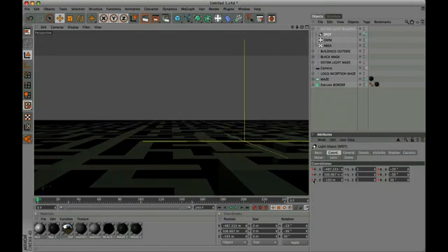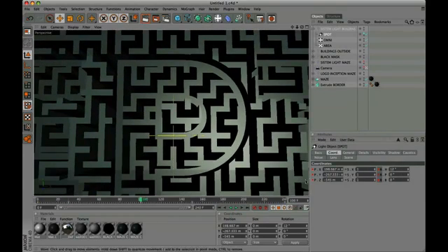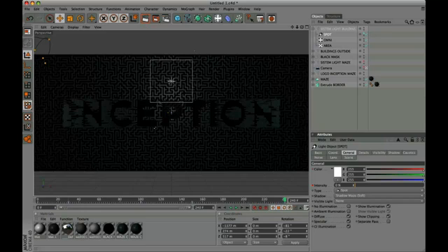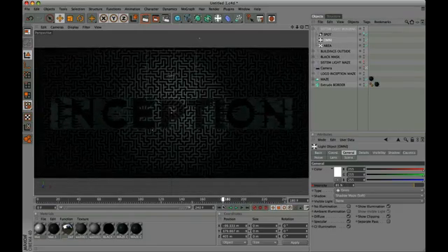In the coordinates panel, delete animation keyframe. Insert value, x, minus 1377. Y, 274. Z, minus 517. Rotation, minus 81, minus 22, minus 8. We click on the Omni light and change the value from 75 to 55, and the frame from 180 to 60.